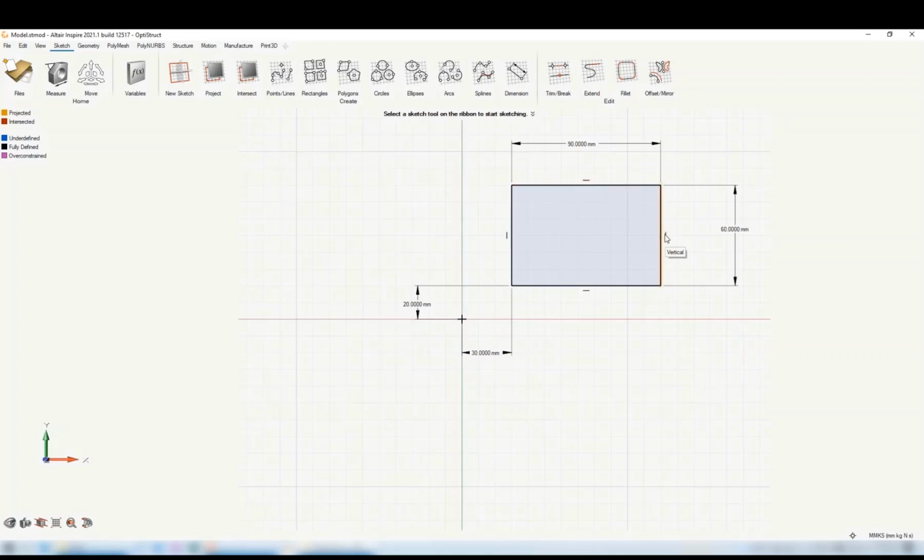Now, you can change those. If I were to right-click on one of those little images of a constraint, you'll see it has a list of constraints in the context menu, and I can disable the one that we put there for you automatically. When I do that, you'll see part of the drawing now becomes undefined or under dimensioned. So now if I grab one of these corners, because that's not a vertical edge anymore, you'll see that it's free to move at any angle we want. If I want to reconstrain that to vertical, I can just right-click on the entity and I can pick from different constraints. In this case, I'll put the vertical back on, and now we're fully constrained again.